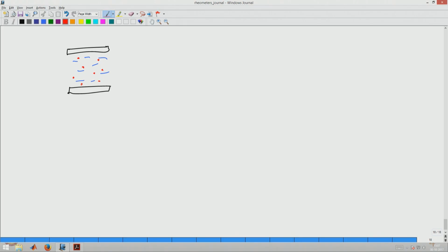We can measure the velocity that way, and if we see that the velocity is what we expect in terms of a linear velocity profile, then we say okay, there are no artifacts in terms of flow being different than the linear velocity profile, therefore we can do analysis. But if using the particle motion we find out that some particles are moving slowly while some other particles are moving fast, then we have basically a banding in the material.